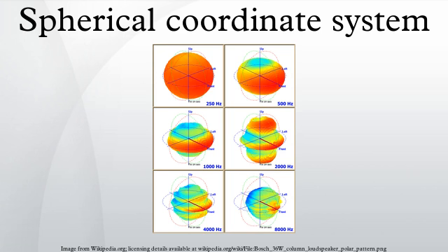Three-dimensional modeling of loudspeaker output patterns can be used to predict their performance. A number of polar plots are required, taken at a wide selection of frequencies, as the pattern changes greatly with frequency. Polar plots help to show that many loudspeakers tend toward omnidirectionality at lower frequencies. The spherical coordinate system is also commonly used in 3D game development to rotate the camera around the player's position.